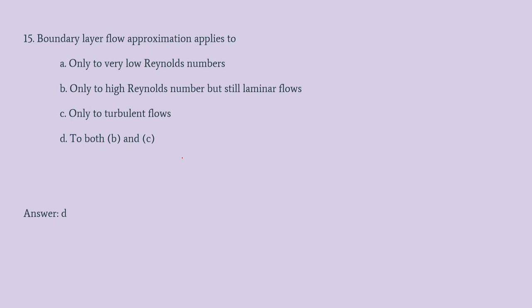So we take the no slip condition as the boundary condition, that is, the fluid layer very close to the boundary has zero velocity, it is stagnant, it is stuck to the boundary. In such cases, there will be a gradual variation of velocities from the solid boundary to the free stream velocity. That portion is called a boundary layer.